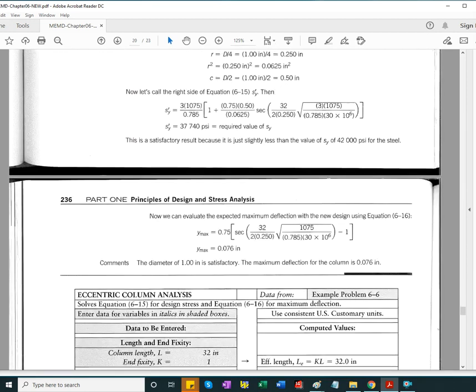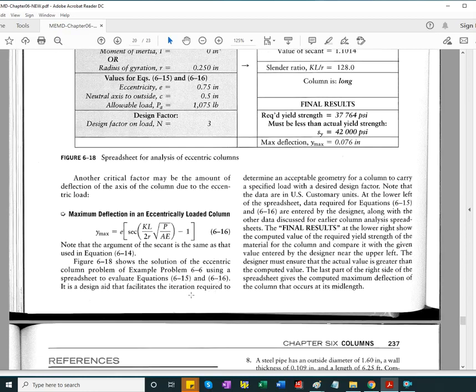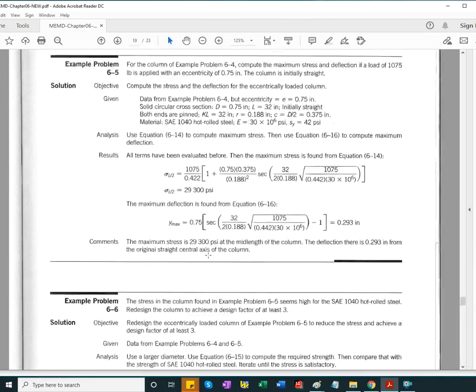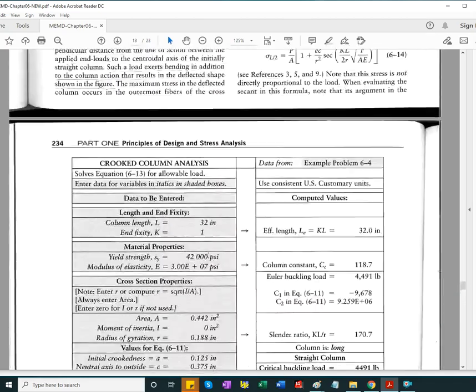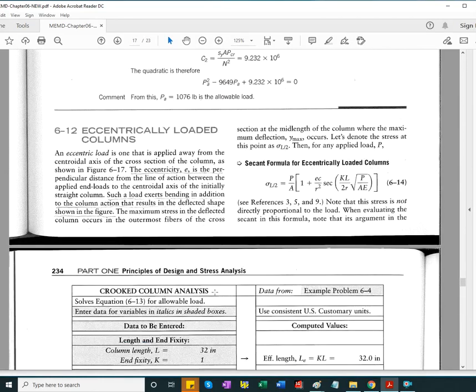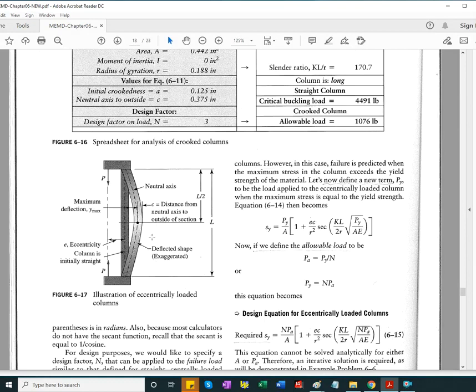There's also, going with the first of the equations introduced, the deflection that is caused by that eccentrically applied load P. So I have an eccentrically applied load P, and I have maximum stress in the middle. Also the middle has the maximum deflection.